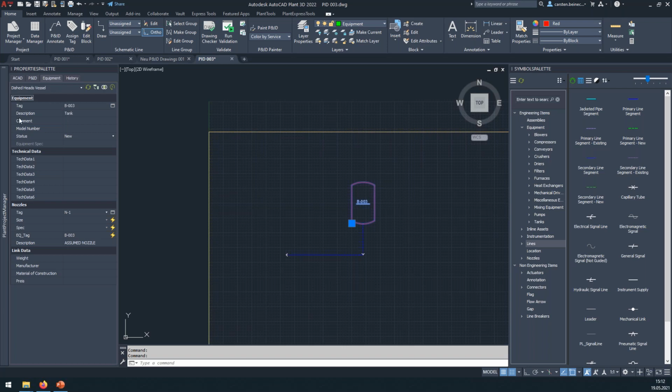And within a group, you can define which properties you want to see and in what order you want to see them. So for example, for an equipment, you can also have a section of nozzles, and well, I only have one nozzle here. Otherwise, like in 3D, you can toggle between or switch between the nozzles. And again, I only have one, but yeah, these are all the properties of nozzle N1, for example.